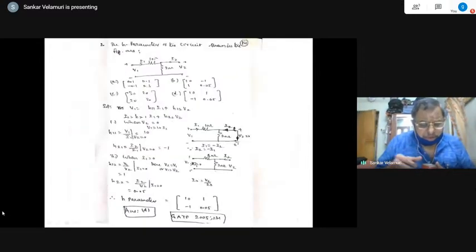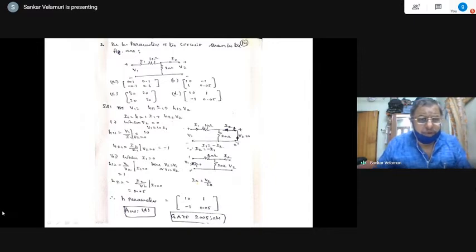So similarly, the next question is the H parameters of the circuit shown in the figure R to be computed. That is given as a multiple choice question in GATE 2005 for 2 marks. So this is 10 ohms. Here no resistance is being given, that is implied that its value is 0.